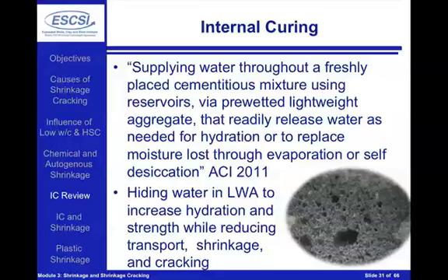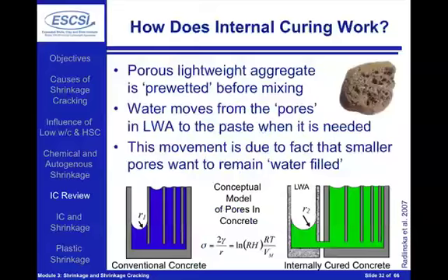So the whole idea here is to use pre-wetted lightweight aggregate that will supply water at the right time to fill in the vapor-filled space that's caused by chemical shrinkage. And by doing this, we're going to improve hydration, we're going to reduce shrinkage, and we're going to cure our concrete from the inside out.